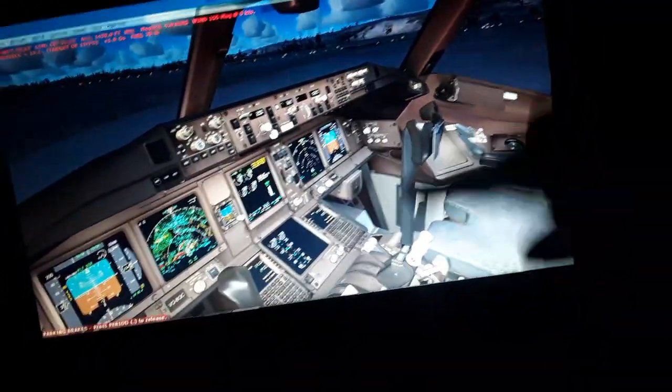You can see the flaps handle over here that increases the surface area of the wing. We're going to have also the mean aerodynamic chord position, the Mach calculated using this data. It is used also to calculate the center of gravity of the aircraft, the mean aerodynamic chord position in percentage of the chord of the wings of the aircraft, and also to set the horizontal tail stabilizer trim position for takeoff, and then for flying. So we're going to use all this data using the flight management computer. It's going to give us the takeoff speeds for this runway, the V1, V rotate, and V2.